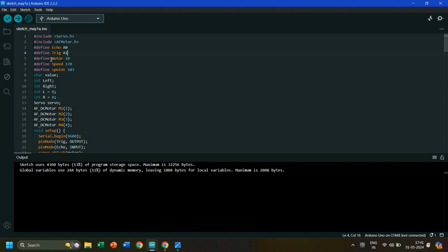Now let's define a motor pin. Let's just skip a few lines to understand what this line is. Now servo. A servo has a VCC, ground and a signal pin, right? Now where is this signal pin placed? This signal pin is placed in the 10th pin of the Arduino header. But while connecting, you can just place the header. That is because the header pin is connected to a few pins of the Arduino which are directly giving the signals to the header.